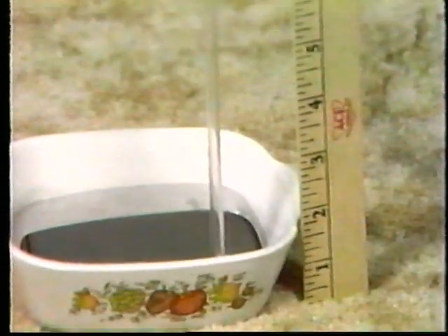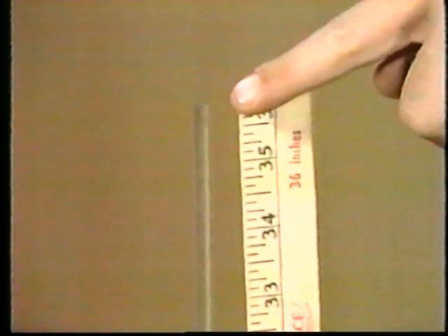To explain vacuum a little better, let's look at this system. We'll use a glass tube set in a bowl of mercury again. As long as the top of the tube is open to atmospheric pressure, as you see, no mercury is forced up the tube because the pressure on the surface in the bowl is balanced by the atmospheric pressure pushing down inside the tube.